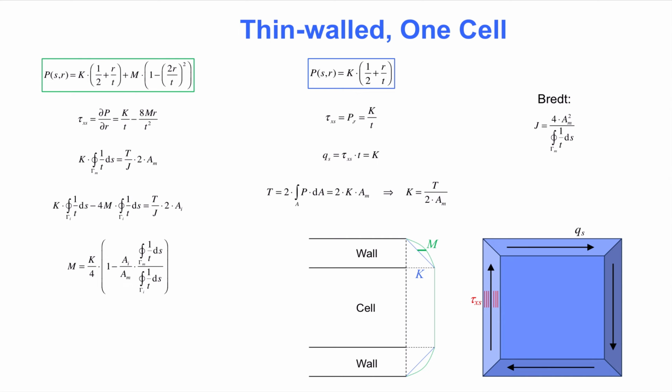As a result, the stress function in the top left corner matches the stress function marked with the green color in the figure. Two equations are required to determine the constants k and m in the stress function. To that end, two continuity equations are established. One of these could be replaced by the original differential equation from earlier in this video, but an important point about the constant, m, is better made with two continuity equations.